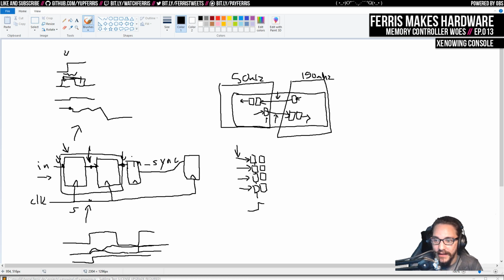So it might be that, let's say this transition from the number 3 to the number 4, which would look 100 instead of 011, or 4 to 3, then you have multiple of these bits changing for that clock, and then you might get one of the bits captured and one isn't by the time you get the value on the other side of the chains. And that's obviously bad, because then you get bad values. And again, gray codes and stuff can do that, but you don't want to be using gray codes to encode everything, because that's, again, only safe if you're going to just increment the value. These values could be anything.